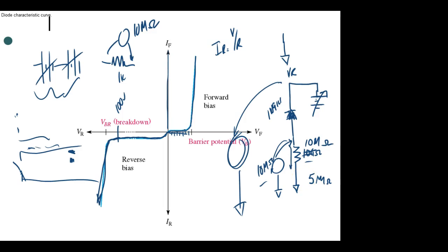You understand? So when we calculate the current on there, we're going to use 5 mega ohms, and that's pretty much the resistance of this meter right here. It's about 10 meg. You can measure the resistance of your meter. Just put it on volts, get an ohm meter, put it across the leads. Don't hold it or it'll measure you, because it's got a real high resistance. And you can measure what loading effect your meter has on the circuit. Now, as long as you're looking at low resistance circuits or low impedance circuits, we can ignore the loading effect of the meter, right? You understand?